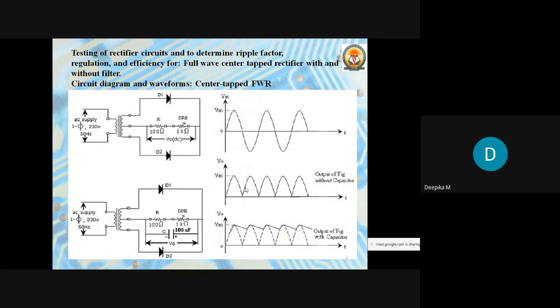You can see here, this is not exactly DC. It is only a unipolar signal, not a bipolar signal. Yes, that is agreed, but it is still not DC. Why? Because it has ripples or pulses in the waveform. Therefore, to remove these ripples or pulses, we use a capacitor. The capacitor acts as a filter and removes the unwanted signal, like the pulses in the circuit.